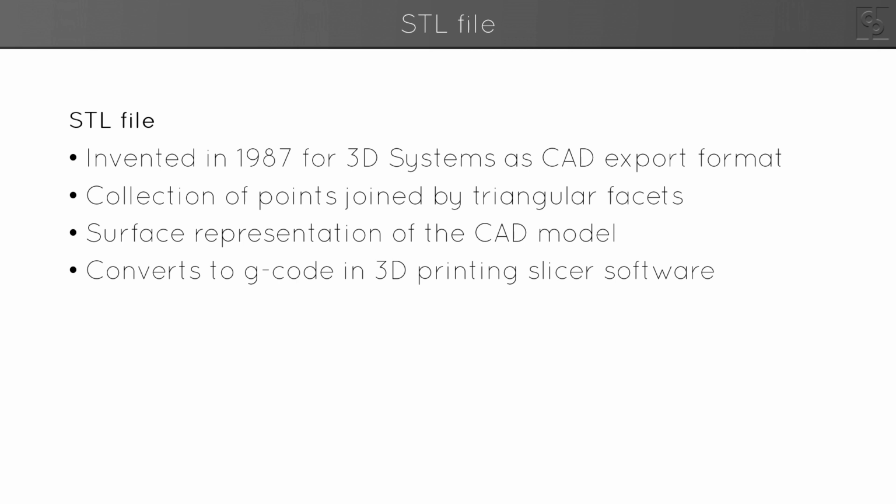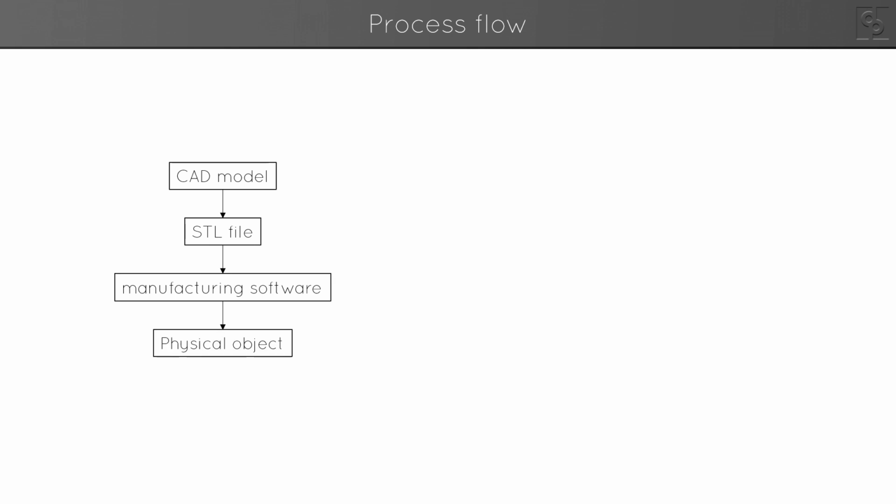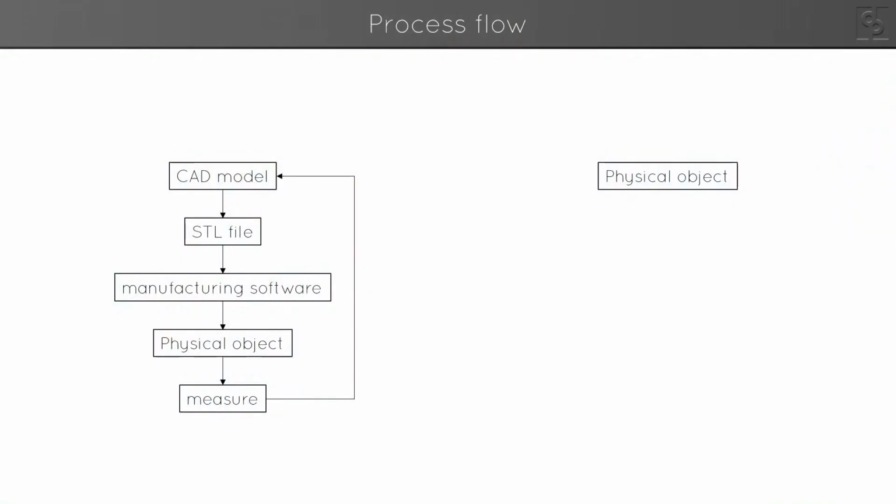The normal process flow is to put all the design and engineering ideas into the CAD model and then make a physical version of that and use the model as a reference when you measure the physical part. When you're building a CAD model from a scan, sometimes called reverse engineering, you probably have limited or no knowledge of the original designer's intentions. You can't tell whether the scanned part is right or wrong, but you're going to trace over it anyway to build a new CAD model.